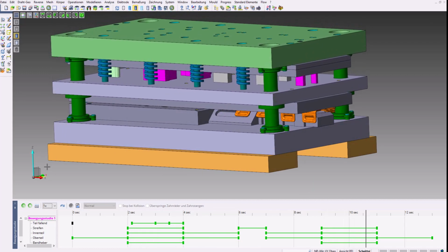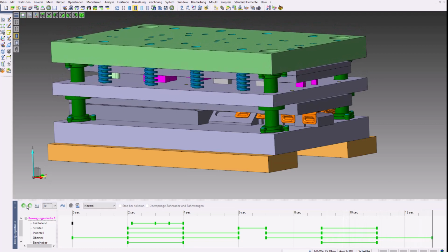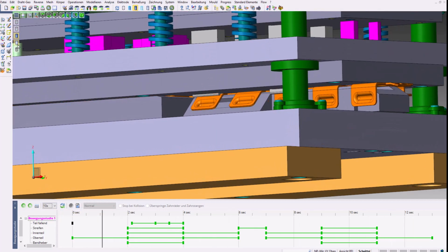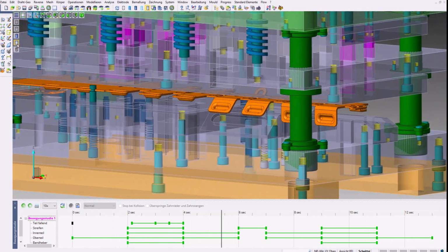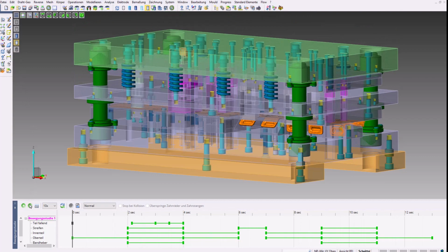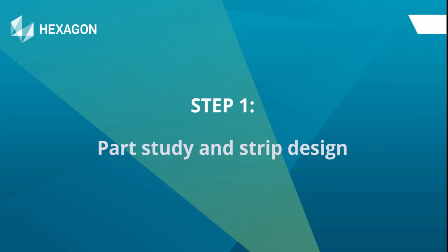During the progressive die stamping process, a stock strip moves the part through a series of individual stations, each performing its operation on the workpiece, such as flanging, punching, forming, and drawing. As the workpiece advances through each station, it progressively assumes the intended dimensions and contours.